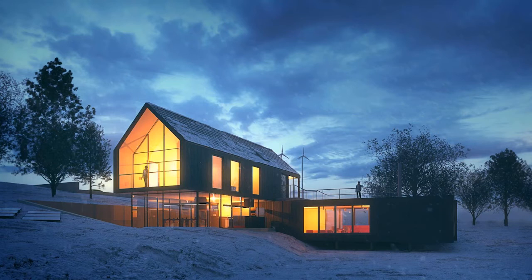If you've got just a generic fixture in there and you haven't specified an IES light, we'll use the generic IES file. So important to note that, and what we've done is just made it a nice warm yellowy orange color, and that warms up the interior view, and that's what you're seeing inside of the scene here. We've got standard V-Ray glass that we've applied to the glazing itself. One of the things that V-Ray does very, very well is glazing, and our architectural glass VRMat that ships with the product is what we're using here.